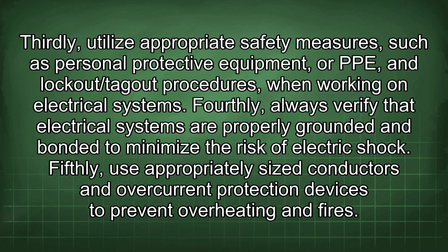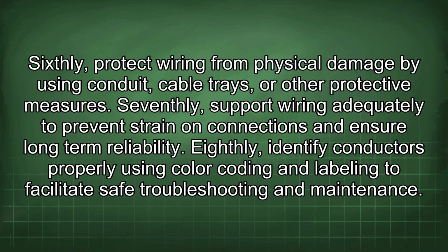Fourthly, always verify that electrical systems are properly grounded and bonded to minimize the risk of electric shock. Fifthly, use appropriately sized conductors and overcurrent protection devices to prevent overheating and fires. Sixthly, protect wiring from physical damage by using conduit, cable trays, or other protective measures.